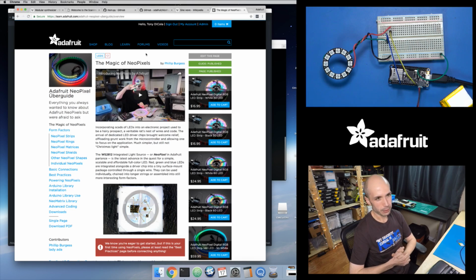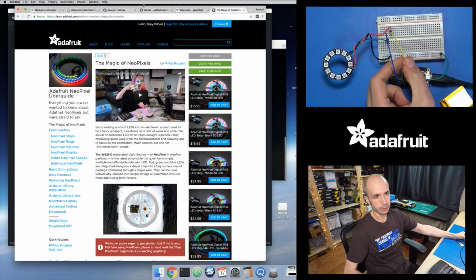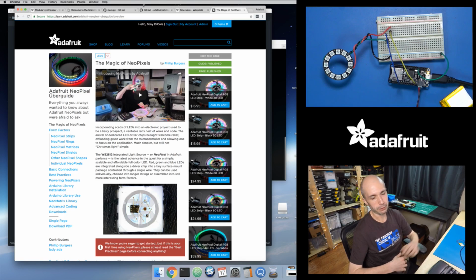So if your pixels don't work, take a really close look at how to power the pixels. There are a few things that I mentioned, and when we look at the code, I mentioned some guides. So if you have to use a 5 volt power supply and 3.3 volt I/O logic, you can add a diode in series with your power. You need a beefy power diode because it's going to have all of the current going to the NeoPixels going through it. But that will drop down the voltage by like 1.2 volts or so. So that will basically reduce the voltage of your 5 volt power supply down to like 3.7 volts-ish. And that'll be good enough also to drive them.